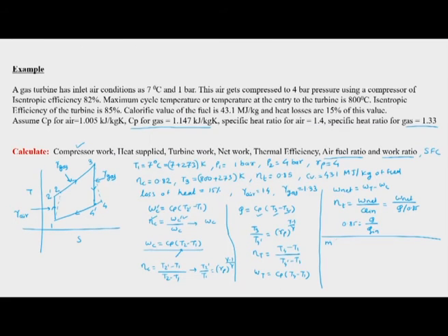If we apply energy conservation, then the mass of fuel is burnt and releases calorific value amount of energy, and it was used to heat the mass of air plus mass of fuel from T2 to T3, but only 85% was used.